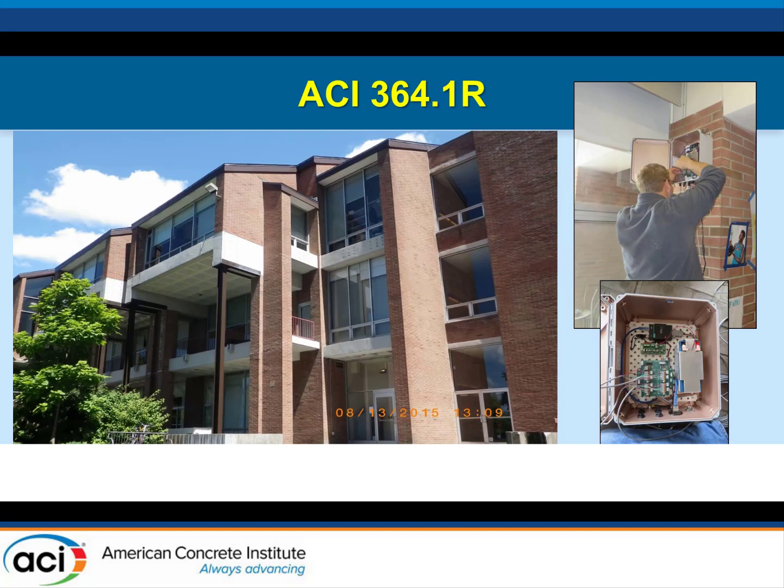So this is a broader scale picture of the structure on the left. One of the things that really started happening was the cantilevers started deflecting, and there were patterns of cracking developing in the brick masonry. In this case, we've gone ahead and installed steel columns underneath the cantilevers. They were not snugged up tight, so there were gaps to allow the continued deflection to occur.